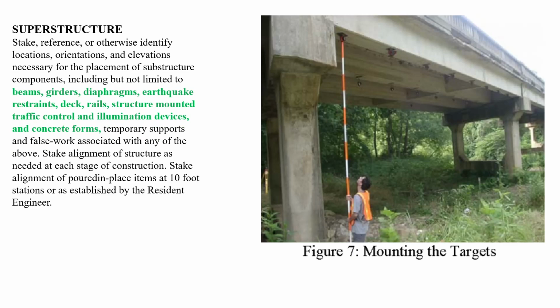Superstructure. Stake reference or otherwise identify locations, orientations, and elevations necessary for the placement of superstructure components, including but not limited to beams, girders, diaphragms, earthwork restraints, deck, rails, structure-mounted traffic control, and illumination devices, and concrete forms, temporary support and false work associated with any of the above.